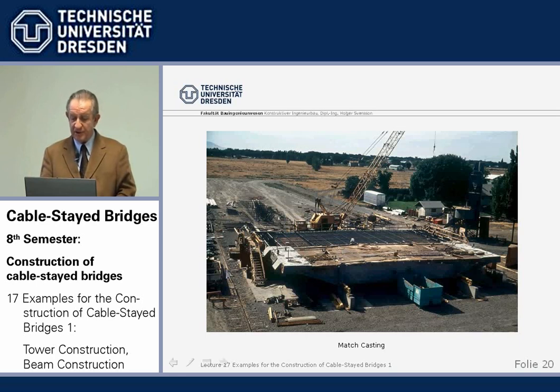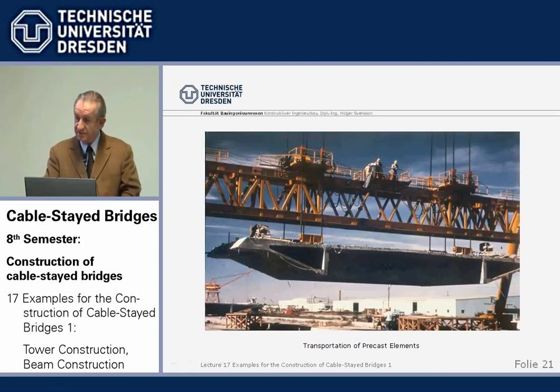In order to have a good fit here, we used what we call match casting, meaning the new element is cast against the end of the element before. So if we have a little deviation in here, that's exactly taken up by the new element. So they are match cast against one another, and they must fit. And so they did, actually.